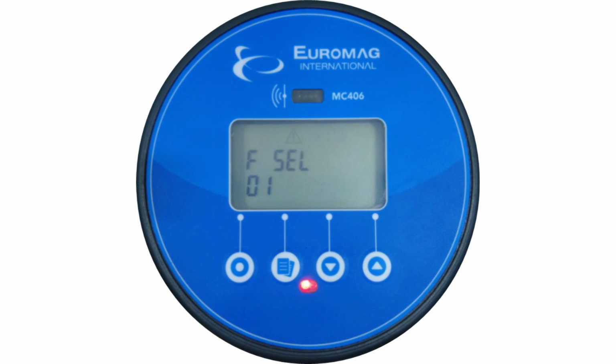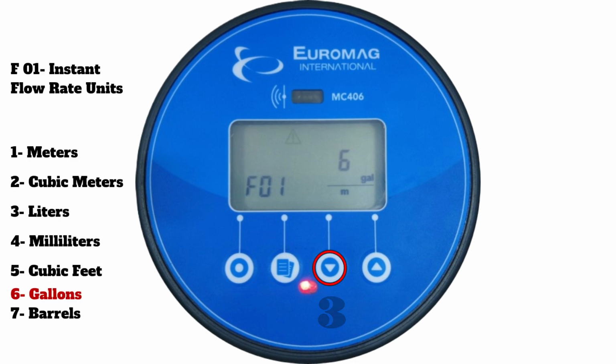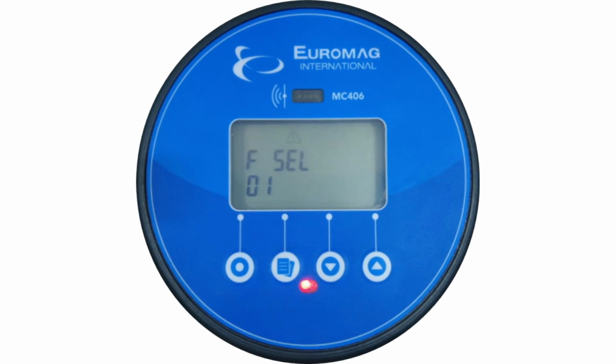Excellent job getting to this point. The display will show F-select 01. To access function number 1, simply press the number 2 button one time. You are now in function number 1 and can use the number 3 button to decrease the value or the number 4 button to increase the value. After you have selected the preferred units, be sure to hit the number 2 button to lock in your changes and go back to the F-select screen.